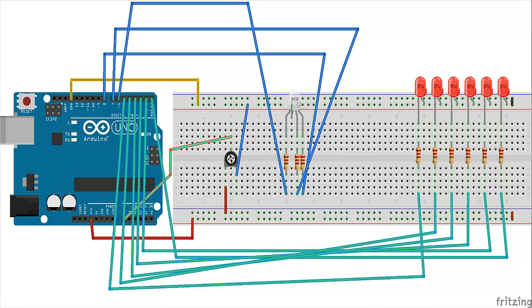This diagram shows the schematic for the circuit. I used a program called Fritzing for this. You can download it off the internet for free. It doesn't have the exact schematic for the Netduino, but it does have the Arduino. Fortunately, the I/O ports are pretty much the same, so you can see what I've wired up here in terms of the various wires. It shows the potentiometer, it shows the multicolor LED, and it shows the regular single color LEDs. For your work, you'll probably want to use a package like Fritzing so that you can document your circuits and be able to save them away, and so that you can recreate them later as you need to.